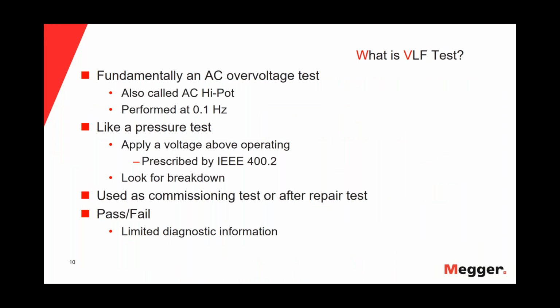What is the VLF test? Let's start talking about the VLF test. The VLF test is fundamentally an AC overvoltage test. It's also called AC hipot. And the frequency we use for this AC overvoltage test is 0.1 Hertz.